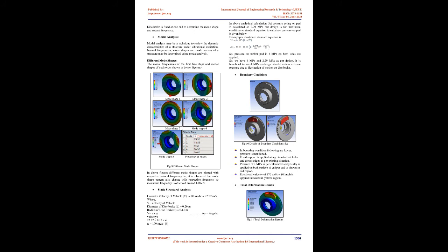7. Topology optimization. Topology optimization is a mathematical approach that optimizes material layout within a given design area, for a given set of loads and boundary conditions, such that the resulting layout meets a prescribed set of performance targets. Basic theory. There are 3 types of structure optimization: size optimization, shape optimization, and topology optimization. These 3 optimization ways correspond to the 3 stages of the product design methodology, namely the detailed design, basic design, and conceptual design.